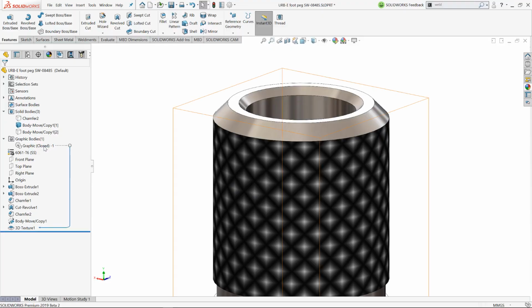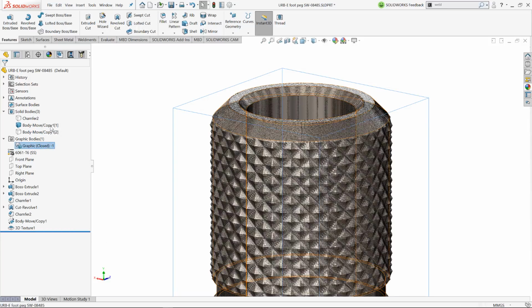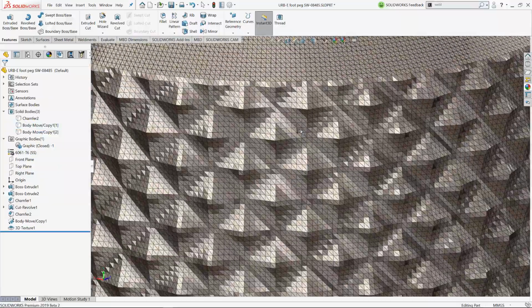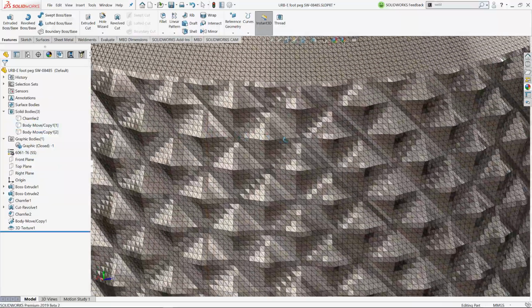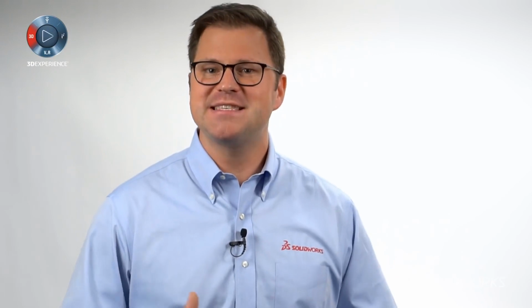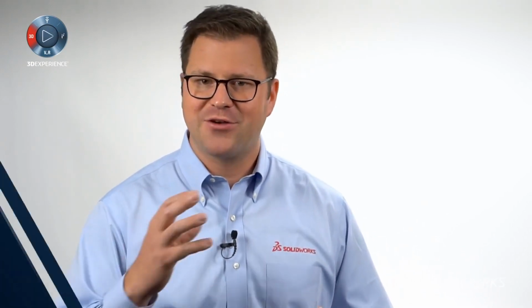3D texture requires converting the work body into a mesh body to apply the texture. The result can be saved right to STL for 3D printing. The original solid B-Rep body is hidden. You can continue to convert to a solid mesh body and leverage the workflows enabled by 2018. Part modeling, it's all about the flexibility of creating geometry and speed in capturing accurate design intent.